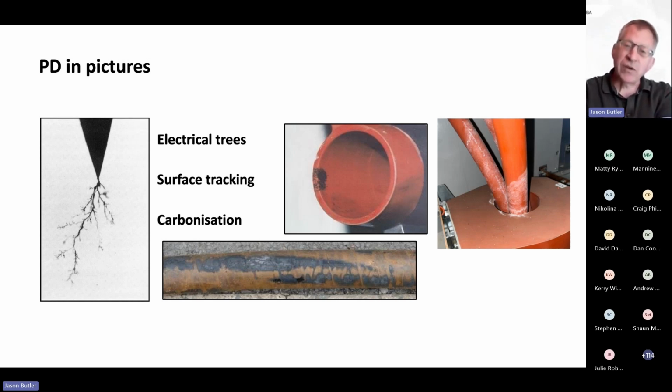Again, partial discharge monitoring, because it's non-intrusive, because it's done live, you can do it quickly and you can narrow down your focus to where you need to be putting your engineering effort. And so when you do have to go intrusive and you've got all your safety measures in place and you've got your PPE on, you can then actually identify it quicker.